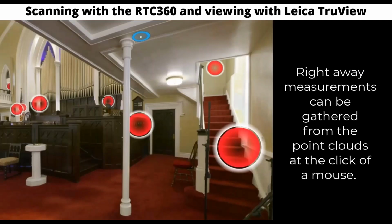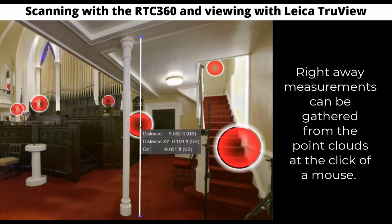Now, I'm going to talk a little bit more about this TrueView software because this is an absolutely awesome piece of software. You saw that we just took a measurement using the TrueView software. Now, the beauty of the TrueView software is it offers the designer, as they are modeling, tremendous views and the ability to look at everything they need to look at. So I typically, if I'm modeling, have TrueView up on one screen and Revit or whatever I'm modeling in on the other screen, so I can kind of move around the point cloud and look at the photography.